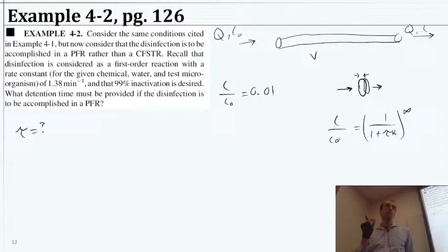And that's the real key, right? That's what changes it from just sitting there to being in a reactor that has continuous flow, okay? So we still definitely need tau as V over Q, but where we put it is essentially dictated by the t that we would normally use for a batch system.